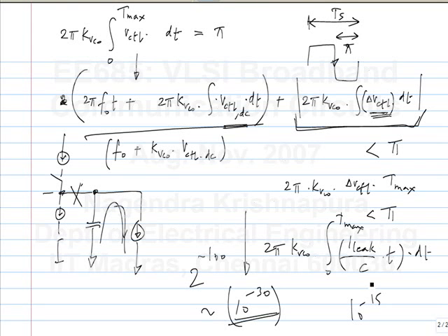But I mean, it's not that you add some other block and make it more robust. If the VCO is stable, it doesn't have any temperature drift, it will do it. But this is a more fundamental problem. When you have no transitions, you can't measure phase, okay? So you take care of all of the practical issues, like you minimize leakage, you minimize the other sources of error in the V control, you don't want any noise coming into V control, you minimize all of that. But there will be some limitations simply because if you don't have any transitions, you can't meaningfully measure the phase.